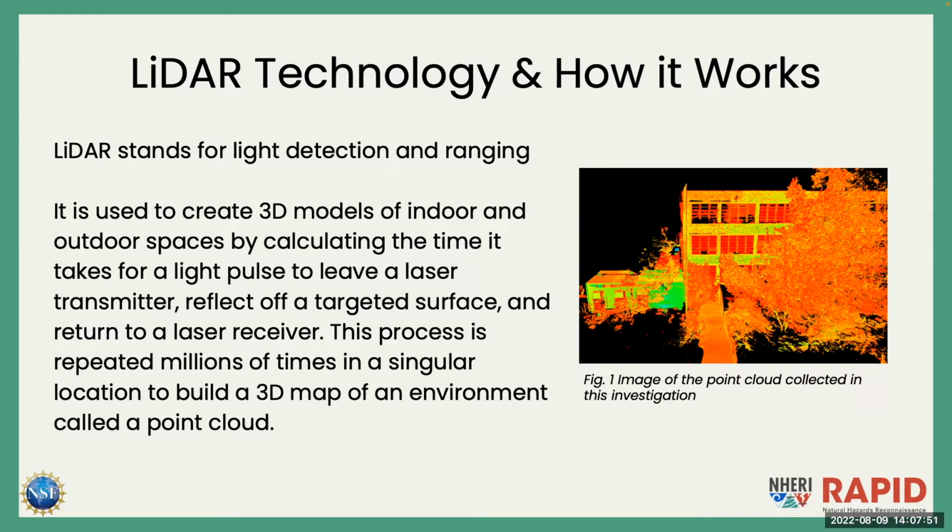It's used to create 3D models of indoor and outdoor spaces by calculating the time it takes for a laser to hit an object, bounce off that object, and be received by a laser receiver. The process is repeated millions of times in a single location, and it builds a really cool 3D point cloud detecting the space around it. So the word point cloud is really important here, and we're going to use that throughout the presentation.